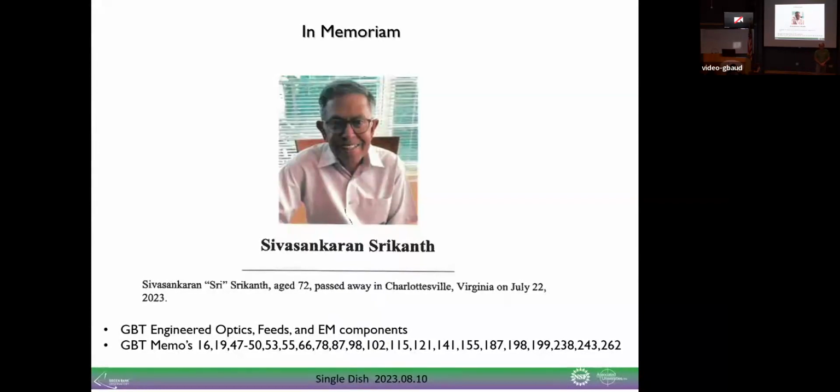Is RFI ever a consideration for deciding to select linear or circular? Not really. RFI is a problem no matter what. For instance, the S-band receiver has a cryogenic notch function for XM satellite. Fortunately, in the quiet zone, the RFI is low enough that it doesn't saturate the first amplifier.